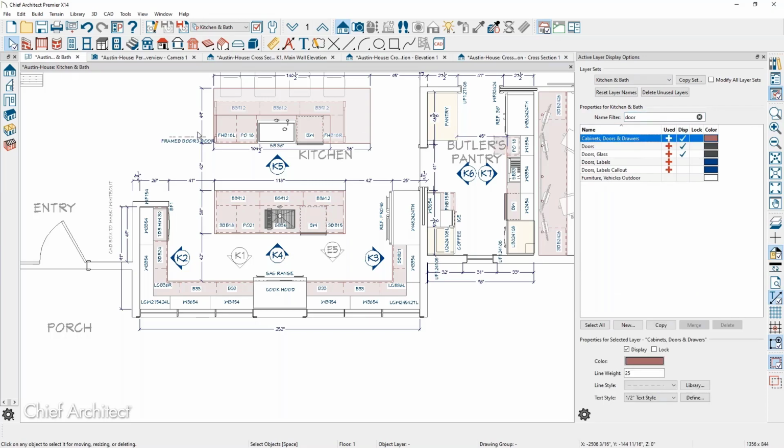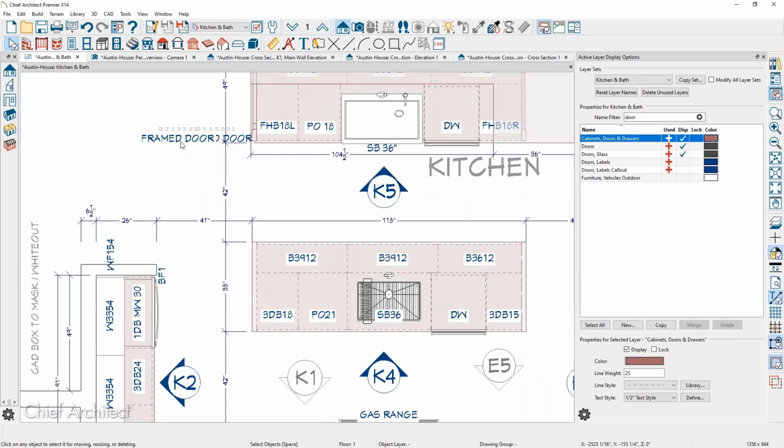Then it will behave just as a regular door would, where you can apply it to a tall cabinet and that sort of thing. If you go through that process, I'd recommend watching or learning about stretch planes for symbol objects, and that will allow your panel to resize uniformly without messing up the thickness of your stiles and rails.